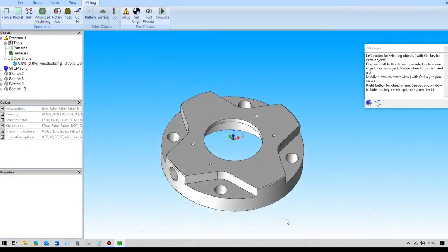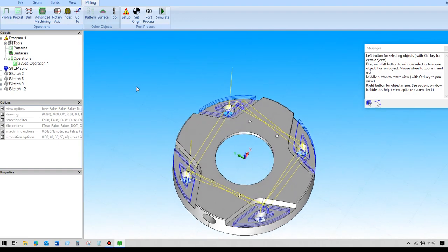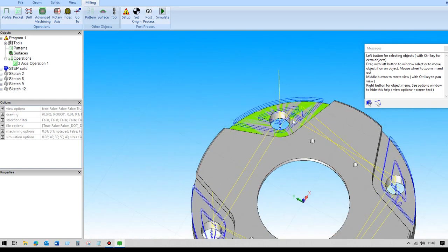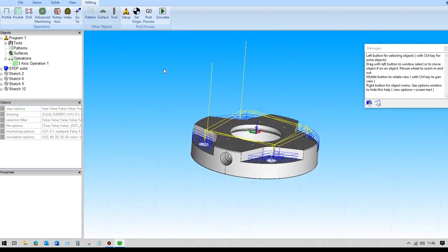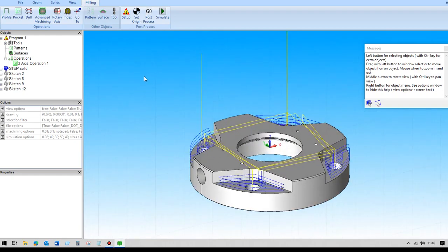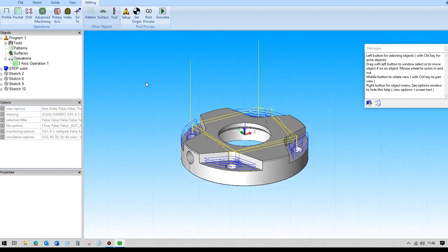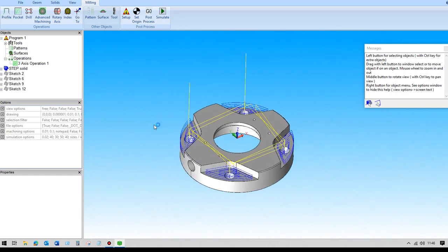So that now creates the toolpath for that roughing operation. Okay, but you may notice that it's also machined down into the cavity, the round holes that were there, because that tool is able to get into those bores. So if we want it to stop doing that, we can either set up the heights so that it only machines from the top down to that face, or a different method of excluding areas is to use